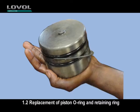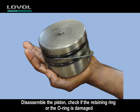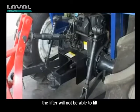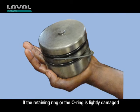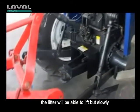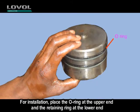1.2 Replacement of piston O-ring and retaining ring. Disassemble the piston. Check if the retaining ring or the O-ring is damaged. If the retaining ring or the O-ring is badly damaged, the lifter will not be able to lift. If lightly damaged, the lifter will be able to lift but slowly. For installation, place the O-ring at the upper end and the retaining ring at the lower end.